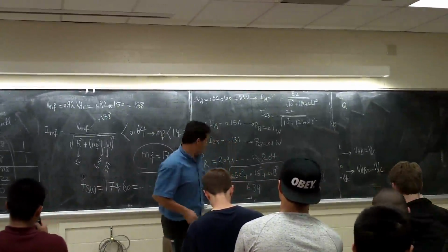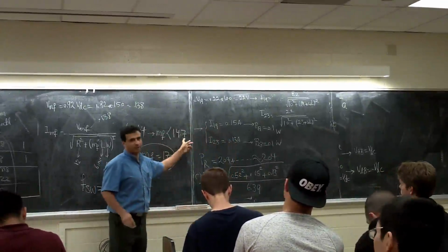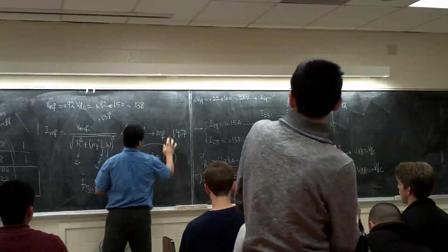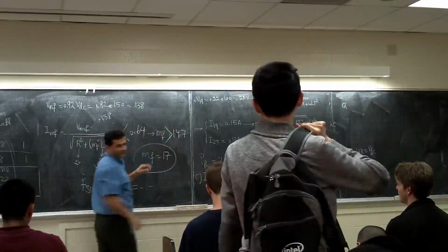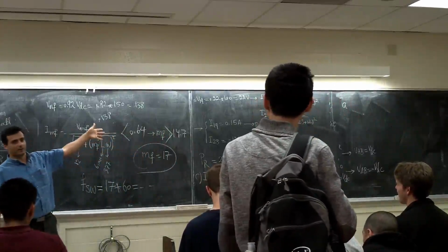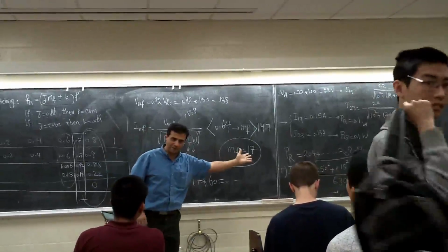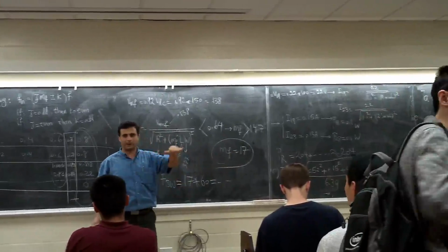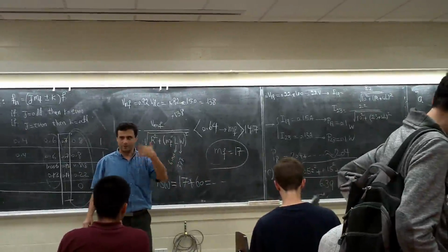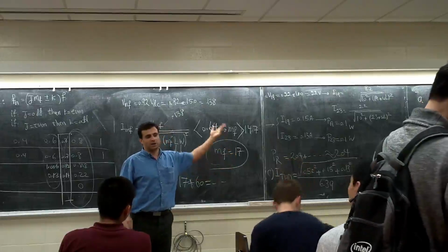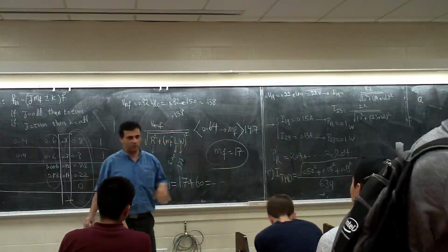So this one said MF should be less than 40.6. No, I'm not here. Hey, here, guys. This is greater than 40.7. So the next one is 15. 15 is pretty close. You can select that one, double check. Most probably you're going to be right at 10%. But usually when you design, you want to have a little bit more. You want to say I'm going with 17 or 19. 19 is better than what I want, right?